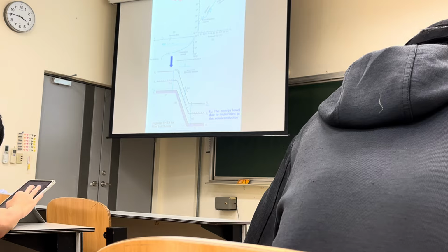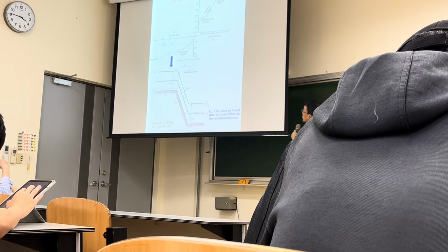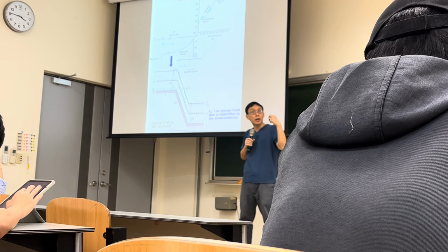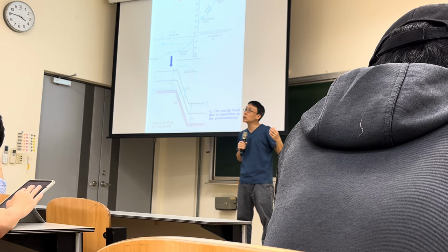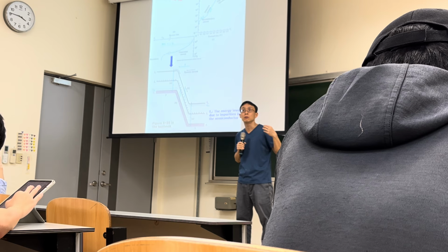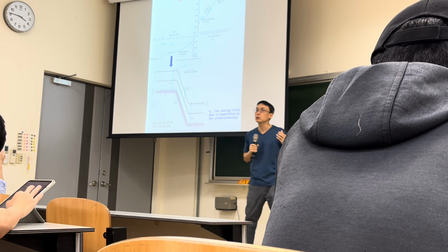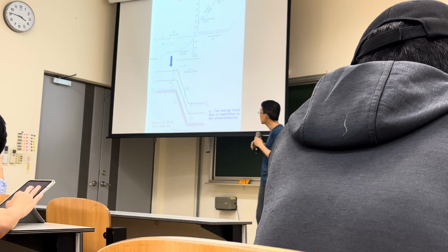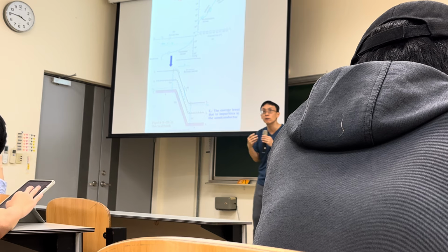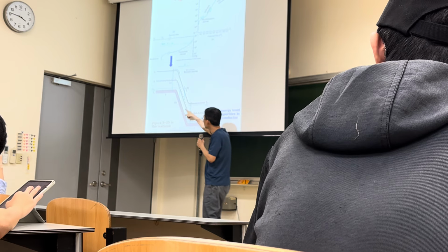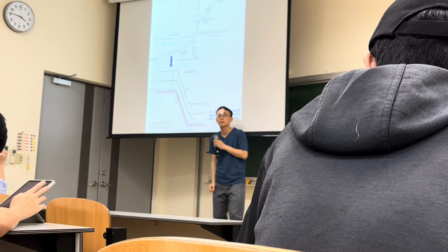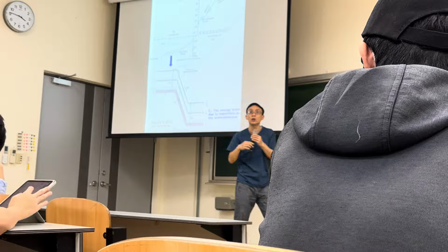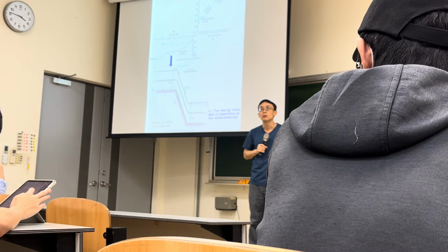So this is the diagram we're going to use to explain the generation current, where you can see in reality, your semiconductor is not perfect. What do you mean? That means you will have more or less impurities inside the semiconductor, which will give you additional energy levels between EC and EV. So these additional impurity levels are real energy levels, right?